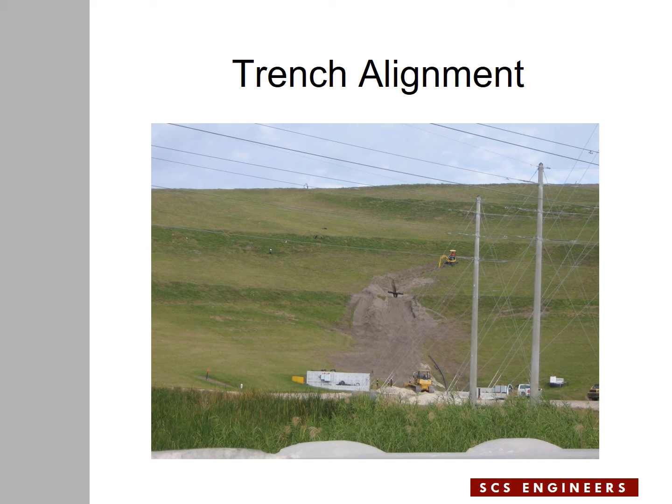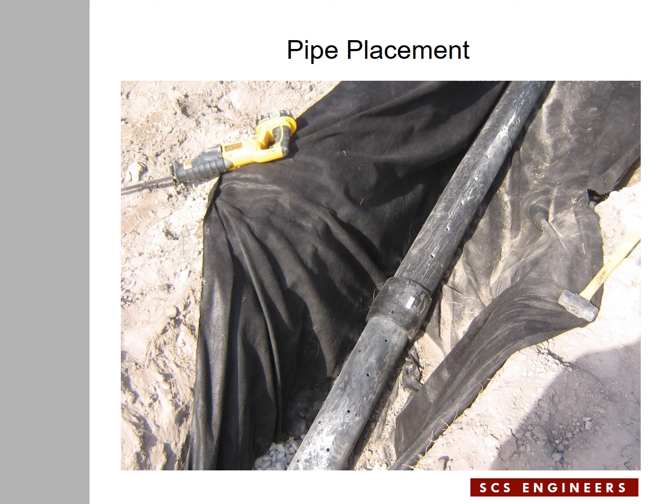Here you see the alignment. The lower part of the slope, the trench is already backfilled. You see the surface of the dirt backfill in the trench, but somewhere up there, when there's a roll of the geotextile placed across the width of the trench, it changes angle because of the center line of the concave surface. The geotextile goes in, directly sits on top of the composite, and the perforated pipe gets installed inside the trench.